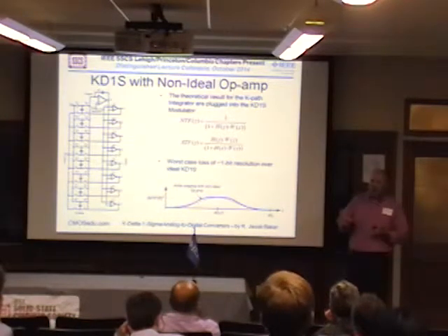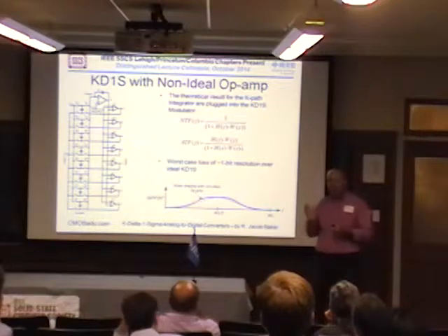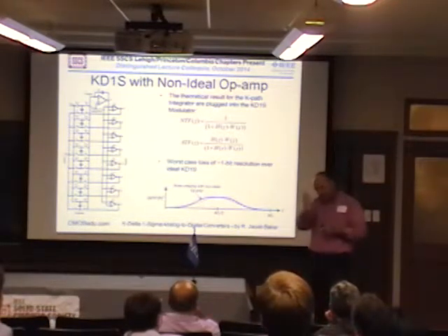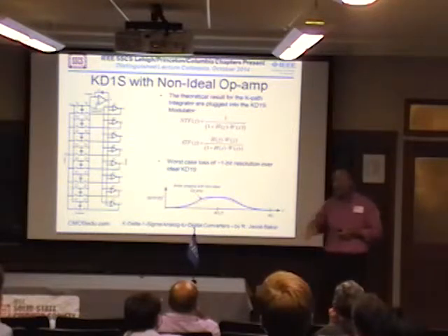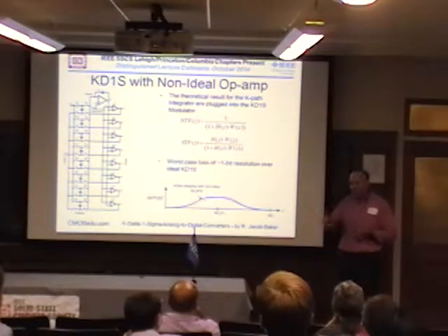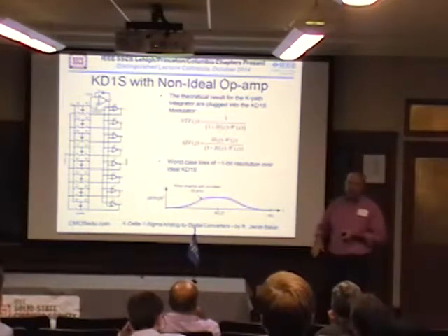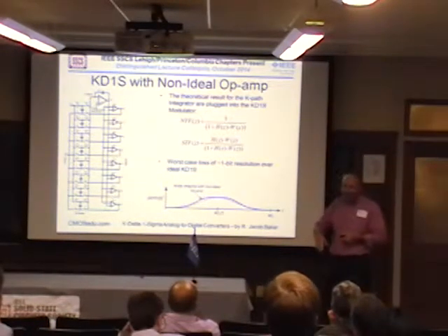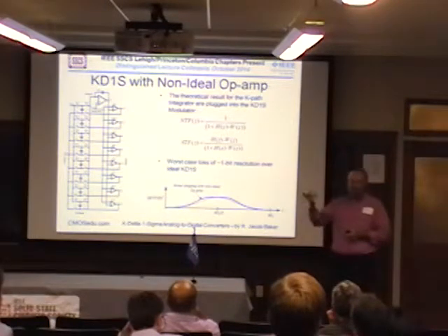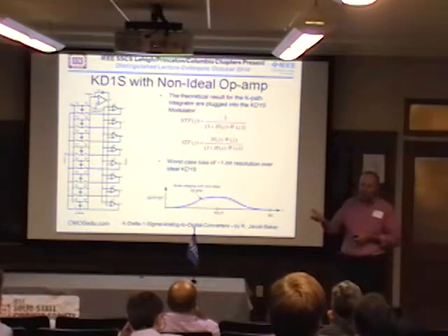If you route your clocks with equal delays and the clock is jittery, with a PDF that's Gaussian in shape, averaging all the different paths will reduce it. It's a common thing in Delta-sigma. It will reduce the effects of clock jitter. So if your RMS jitter is 5 picoseconds and you average 9 paths, I'd pick an easy one, it would be reduced by the square root of 9, or 3. That's under all ideal conditions.